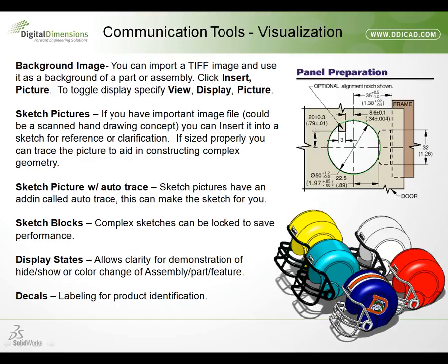But the problem with that is inherent to configurations, and that is when I make modifications to the current configuration, that's where those modifications are. If the top level configuration, which shows the case, isn't currently active, then when I go to the top level configuration, I'm going to need to unsuppress or show the items that I modified in order to have them come into the top level. And for this reason, SOLIDWORKS introduced display states in 2006.